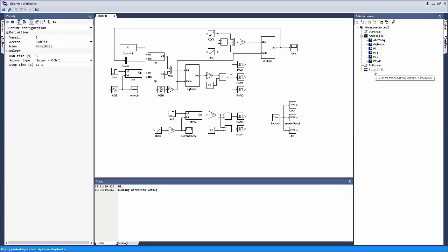Unlike an induction motor, where the rotor flux was induced by the currents in the stator winding, in a permanent magnet synchronous motor, there is a permanent magnet that establishes the rotor flux. Thus, the initial position of the rotor magnet needs to be known because our DQ frame is aligned with respect to the rotor flux linkage space vector.